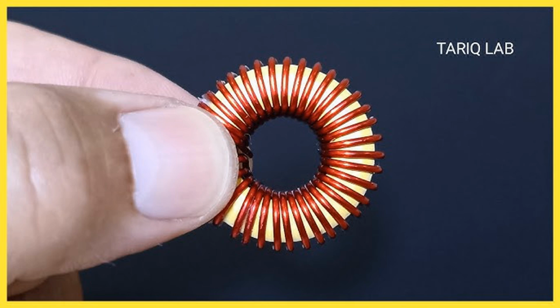LED drivers. Application: inductors are used in LED driver circuits to regulate the current flowing through LEDs, ensuring they operate within safe current limits. LEDs are sensitive to overcurrent, and inductors help to prevent current spikes that could damage the LED. Example: in an LED driver circuit for lighting, an inductor helps limit the current and prevent damage to the LED during operation.